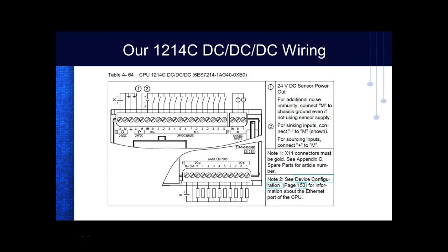Okay, does that make sense? This guy here has an output that's EM. So I could have taken this output right here and connected it and used it instead of this right here. What they're doing here though is they're using an external power supply. Make sense? So here's where I powered up. I put 24 volts in right here. So this is a DC input. 24 volts right here. And then it gives me an output, which is what? 24 volts, right? And then what we could do is take this right here and run it and use it down here. So we can't use this power supply to power our output, right? So what we have to do on our output is have an external power supply.